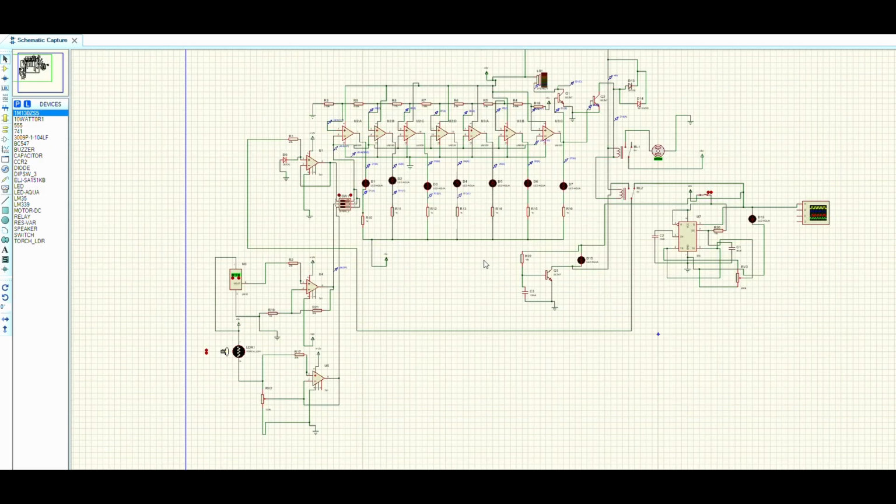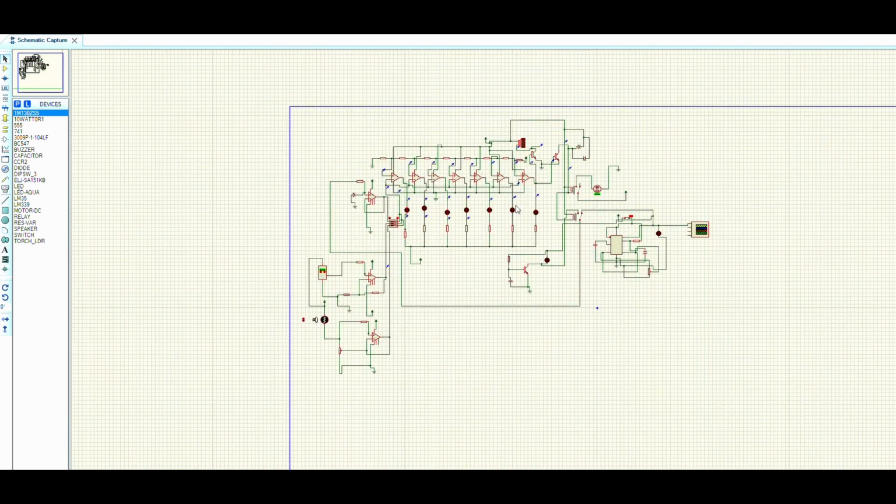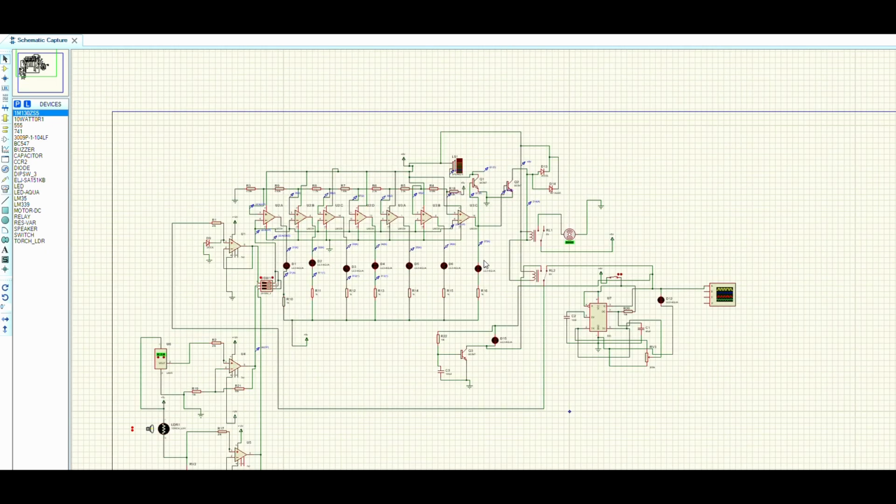We made a working 7-comparator circuit using LM339 ICs in Proteus. Here we have used an op-amp to amplify the input audio signal. This op-amp works as an audio amplifier. There is no proper audio input available in Proteus, so we made a pulse generating circuit which generates a pulse as the audio input, and we will demonstrate how it works.